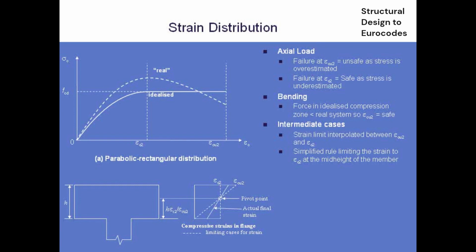What it actually says is, if you have sections which are in overall compression with some bending, or even if you have flange outstands which are wholly in compression with some bending, then you have to work to a new stress limit. This picture is trying to show what you have to work through.